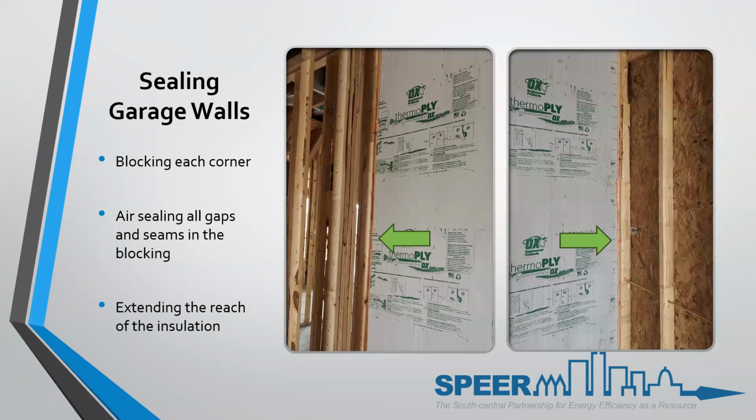The garage wall: these are the corners of the garage wall on the back side, where a conditioned space hits. They blocked each of those corners and put the studs in the right place, pushed to the garage side, leaving the corner to be insulated. As we say, advanced framing, either a 2-stud or the way they installed it on the wall, it actually met on that 16-inch on center. There's not a dead space at this garage wall. Then they put the T-ply in and polysealed the gaps. So having this correctly planned out and well executed is always beneficial for limiting air movement into those walls.